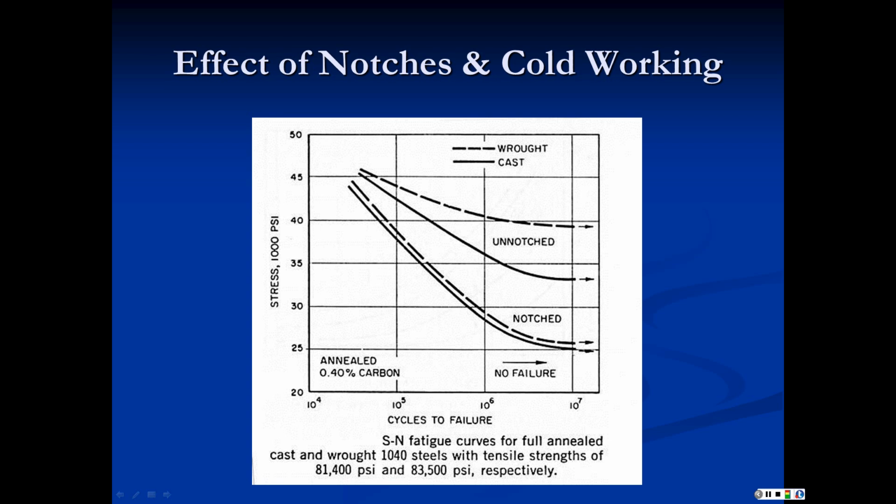And then there's wrought product or forged product, where they take a bar that is larger than the blade, and they hammer it and hammer it until it is the shape of the blade. It's going to be vastly superior. It will hold an edge better, but it's also usually 2 to 3 times more expensive than the stamped materials. So that's the extreme version of a wrought product, and it's been worked into its final configuration.